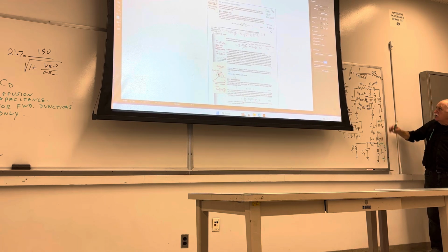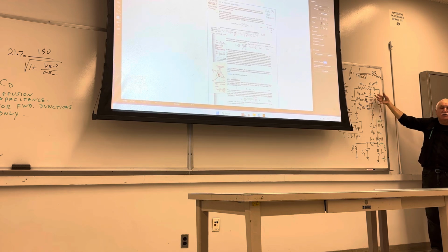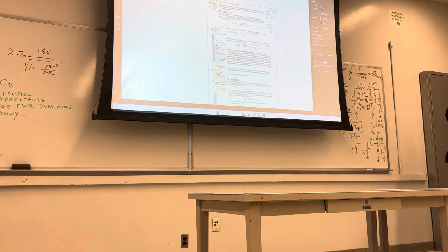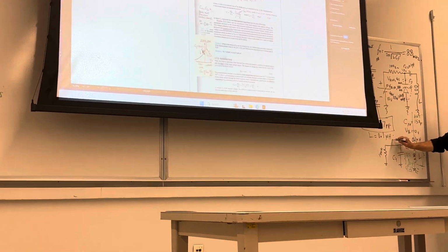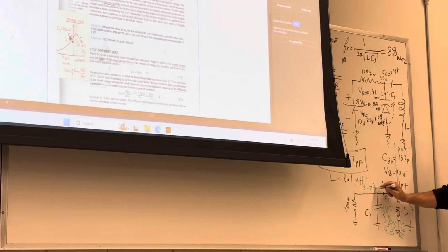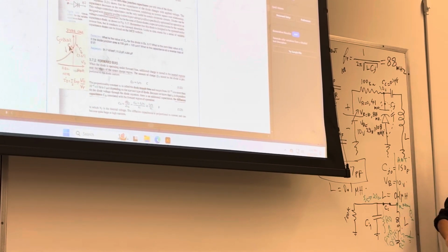But guess what? If you make this guy forward, do you remember the dynamic resistance in a diode? You know that slope, how low it was? It was like 20 ohm, 30 ohm. This diode, in the forward, it will show you the RD. RD, this is the forward dynamic resistance, which is only 5 to 20 ohm, or something of that order.